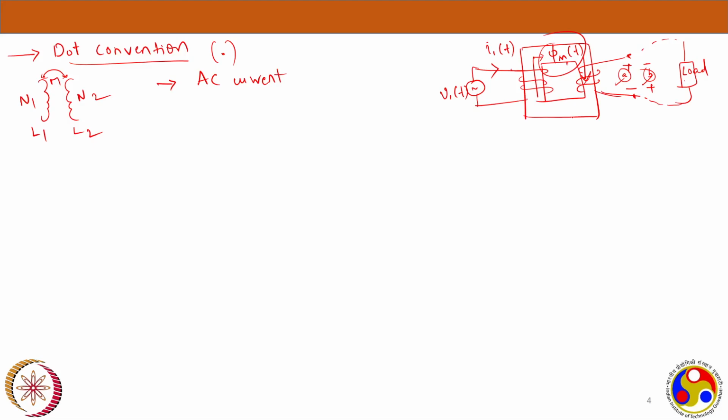That is the effect. What is the cause? The cause is the flux. What is the effect? The effect is the induced voltage being generated. Now, here the effect should always oppose the cause. My induced voltage should oppose the cause, which is the main flux. When I say opposing, it should go in reverse to each other. Now let's take the case B first, with negative and positive.